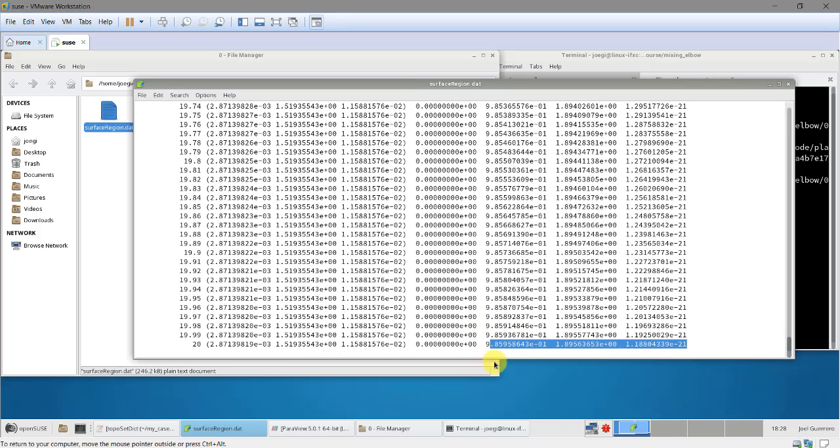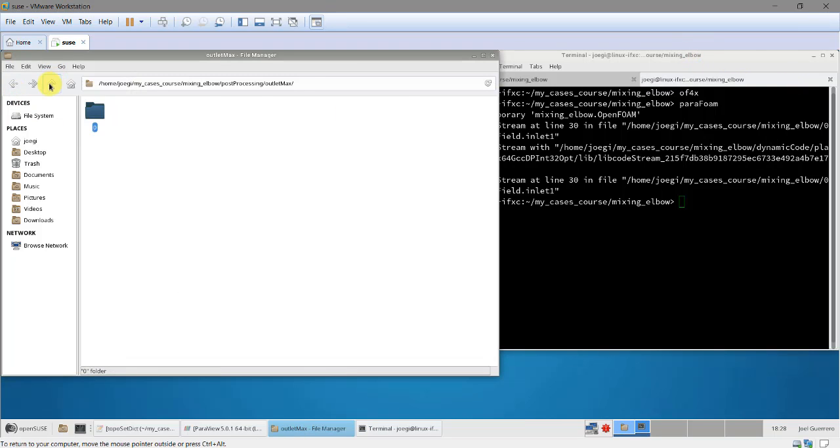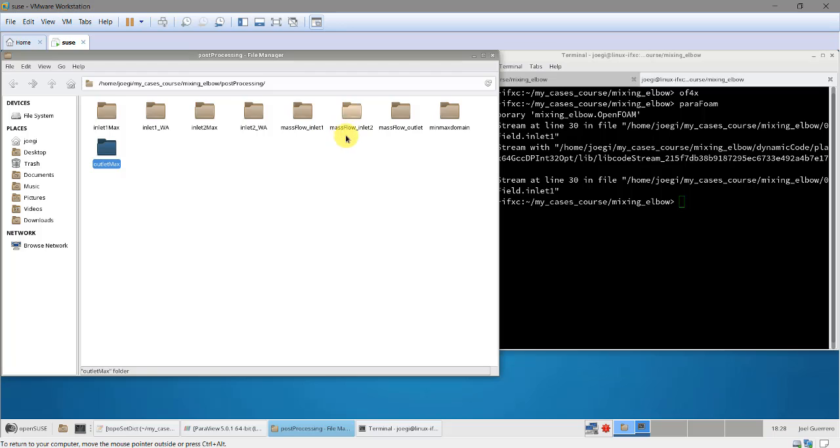So here we know precisely the concentration in a specific patch. Also you can do it in a specific region of your domain. Here we have the mass flows, inlet and outlets. Remember, the method is fully conservative, so whatever is going in is going out as well. So the summation at the end should be 0 or close to 0. Remember, the numerical method produces a certain amount of garbage that we need to live with. So you will not get precisely 0 in that difference, and there are many other functionalities.